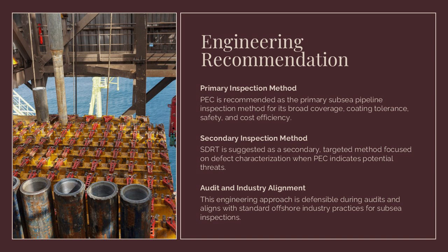The engineering recommendation is to select PEC as the primary subsea pipeline inspection method due to its coverage capability, tolerance to coatings, safety, and cost efficiency. SDRT should be reserved as a secondary, targeted method for defect characterization where PEC indicates potential integrity threats. Speaker notes should emphasize that this approach is defensible during audits and consistent with offshore industry practice.